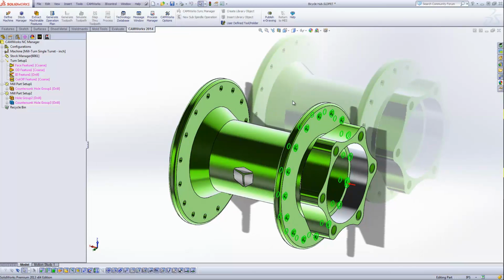So this is the standard process. I'll run feature recognition, and I'll essentially filter out what it gives me. Okay, this is a realistic view as to what feature recognition does. It's going to give me some features that are perfect. It's going to give me some features that are unusable. It's going to give me features that are great, but I'm not going to use them that way, or I'm not going to cut them. So there's always some filtering. I'm going to be removing some features. I'm going to be rearranging features, and I'm also going to be adding my own features. But it's really a shortcut, right? It did a lot of this. It did a lot of the setup for me.